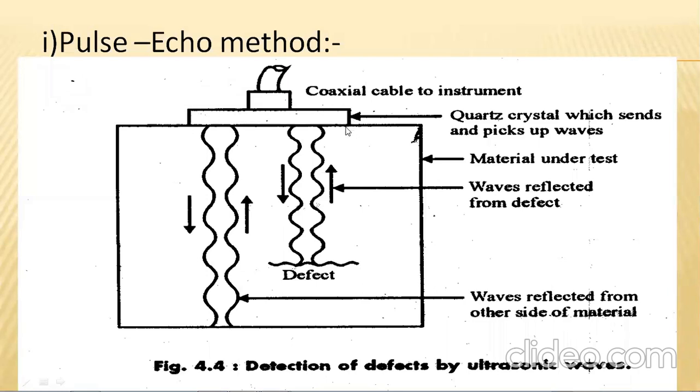So this is the principle of inspection in the ultrasonic testing process. The particular area where the probe occupies the space over the workpiece will generate the waves to a maximum extent, up to the end surface of the object, and hence the return of the waves will be identified. The traveling distance of the waves will be captured on the CRT scale, and the overall depth of the material will be specified in the default conditions. Nothing but the overall dimensions of the material will be specified to the comparator.